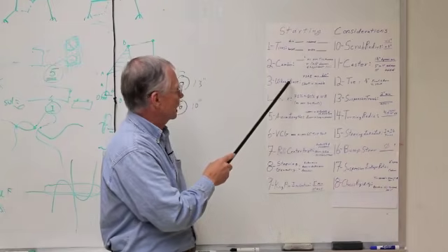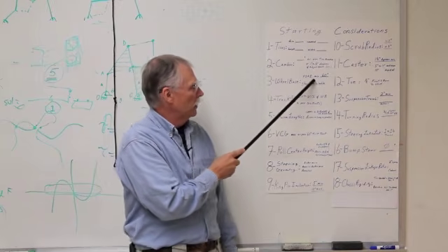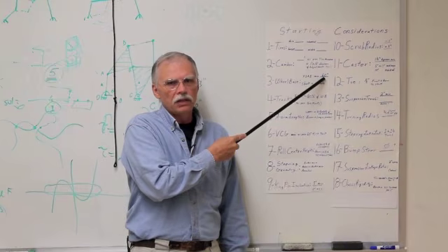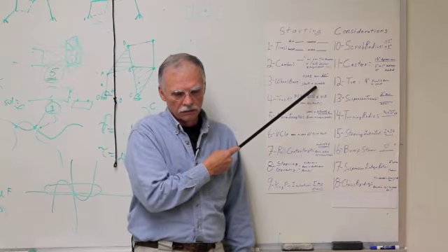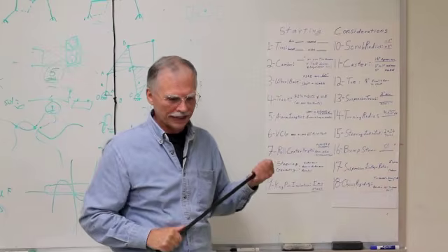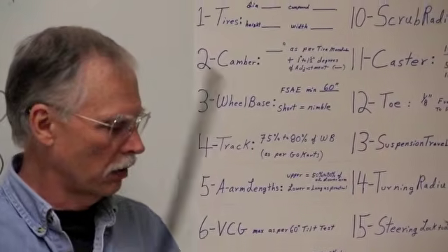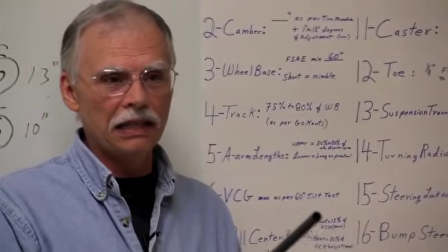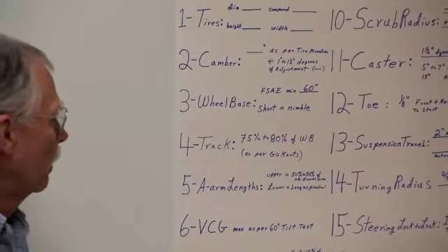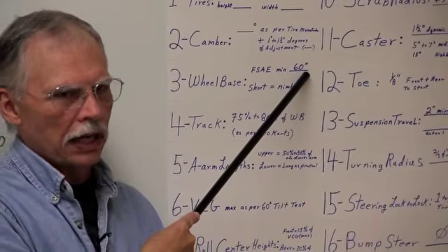1, 2, 3. The next thing we need to decide upon is wheelbase, and it's pretty simple in FSAE. 60 inches is the minimum allowed by the rules. Short wheelbase equals nimble. The car will be operating in autocross conditions which demand the utmost in nimbleness. You're not going to Bonneville. You're not going to Indianapolis. You're not even going 200 miles an hour to a drag strip in a straight line. So you don't need a long wheelbase for high-speed stability because the speeds are so low. What you need is nimble. So 60 inches or slightly over is the best wheelbase dimension.